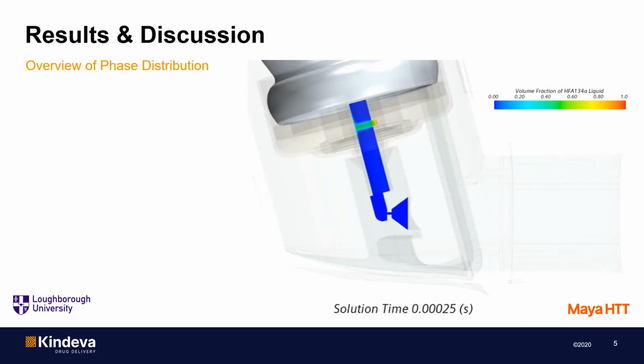As part of the results, first we show an animation of the overview of CFD model predictions. We are going to look at the distribution of liquid volume fraction. The color scale runs from red, which represents 100% propellant liquid, to blue, which corresponds to 100% vapor. Intermediate colors represent mixed liquid vapor region with color scale indicating whether the content is predominantly vapor or liquid.